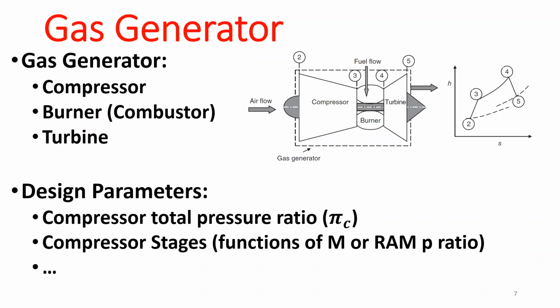I'm not too familiar with the ramjet. Let's go to Ryan. Well, the inlet is designed in a way that it induces shock waves to create pressure across the shock wave, so you don't need an actual mechanical thing. Exactly. So supersonic flow. That's the general answer: in a supersonic flow, you can manage the flow with shock waves. You won't need to include a compressor, right?